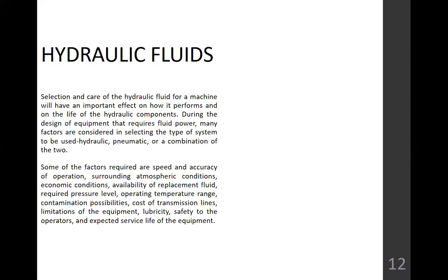Some of the factors are speed and accuracy of operation, surrounding atmospheric conditions, economic conditions, availability of replacement fluid, required pressure level, operating temperature range, contamination possibilities, cost of transmission lines, limitations of the equipment, lubricity, safety to the operators, and expected service life of the equipment.